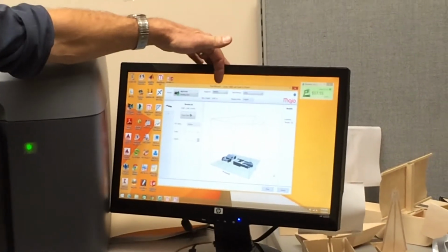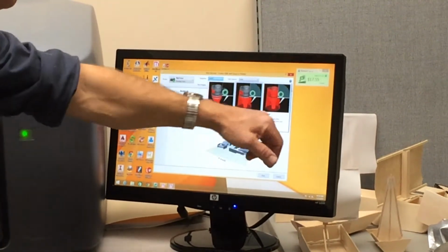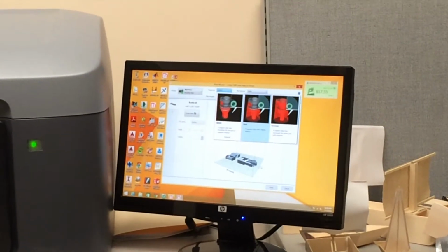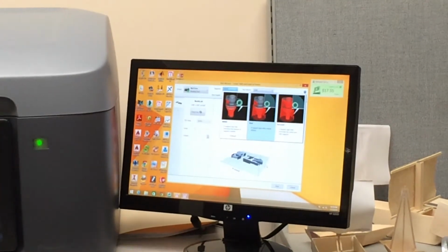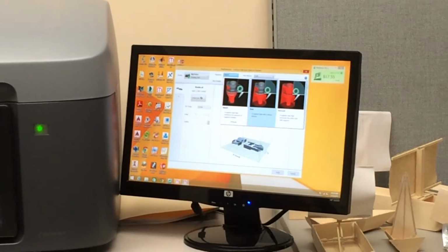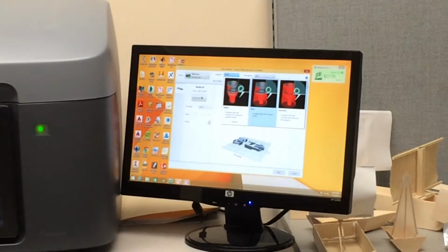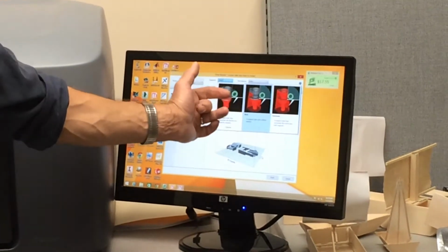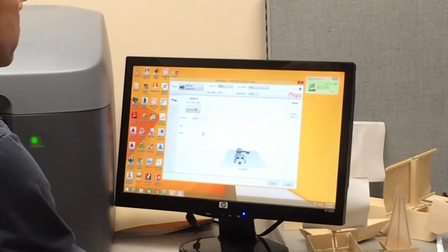All right. The only other things are that there are different ways to view the supports. There are smart supports, basic supports, surround supports. Smart, the program looks at it and says, this is all I have to put in the way of support material. Basic just takes the volume and projects it in the Z and puts everything that's void as support. And the surround encompasses the whole model in support material, right? Smart is usually the best unless you find something in particular that it doesn't work for.